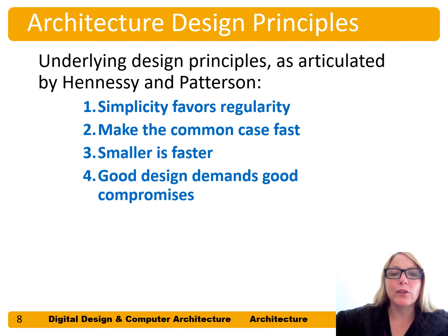And that helps in understanding, building, and debugging the system. Second, make the common case fast. Third principle is smaller is faster. And the fourth one is the catch-all: sometimes we're going to violate these above 3 principles because good design demands good compromises. So that's the caveat that sometimes we won't do those top 3 things.